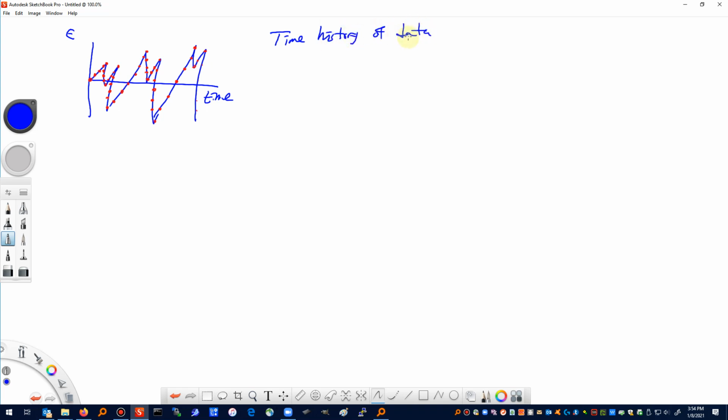Okay, so you'll take a time history of data, and for our purposes, it's going to have a constant digitization rate, or data acquisition rate. But it doesn't have to be. Our time histories will be a constant data acquisition rate, but you can have a variable data acquisition rate. The important thing for us initially is going to be to determine the peaks and the valleys of the time history.